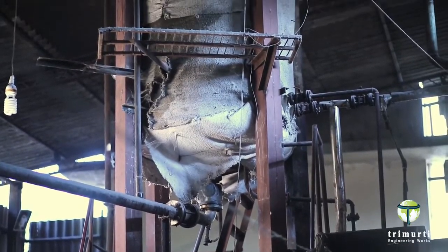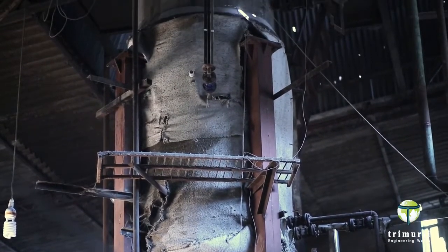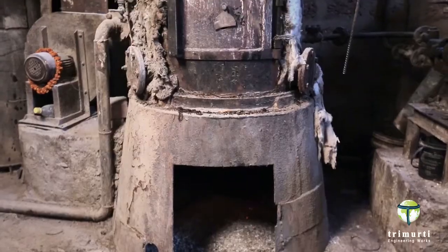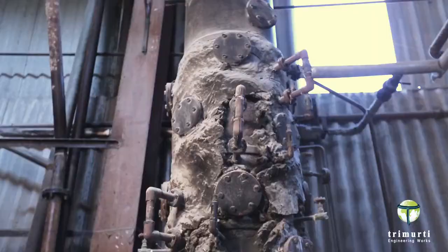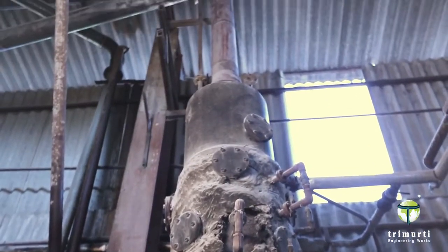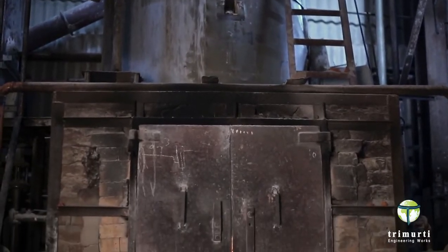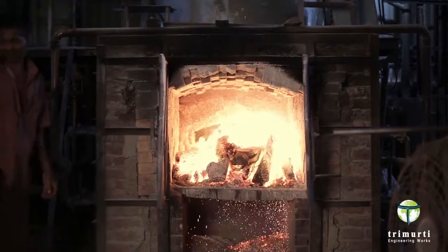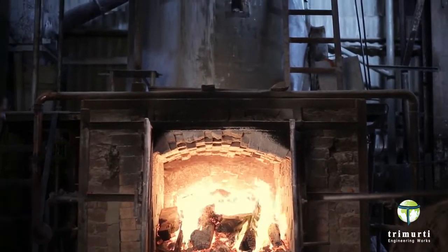In the oil tank, the oil is heated to a temperature of up to 250 degrees, and a defoamer is added to remove the foam from the oil. This entire process is a batch type process. The oil heating tanks are supplied with steam with the help of a boiler. The agents used to fire the boiler are generally wood or the shell cakes.